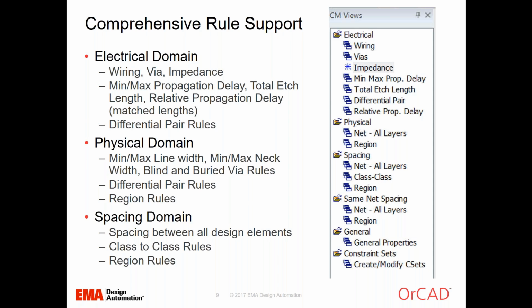The electrical domain is a powerful environment for electrical constraint entry, editing, and management. It includes wiring rules for scheduling, controlling stub lengths and parallelism, and layer constraints. It also includes maximum via count rules, impedance rules, min-max propagation delay, which is a pin-to-pin delay, total etch length, which is the overall length of a net, and relative propagation delay, which is a match delay.